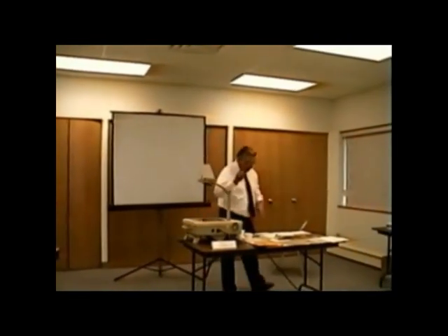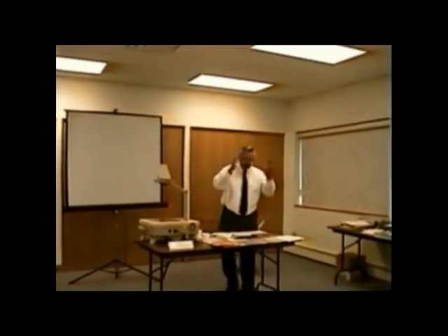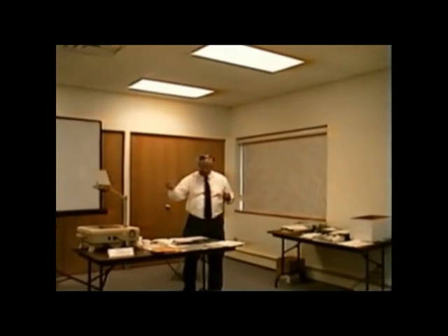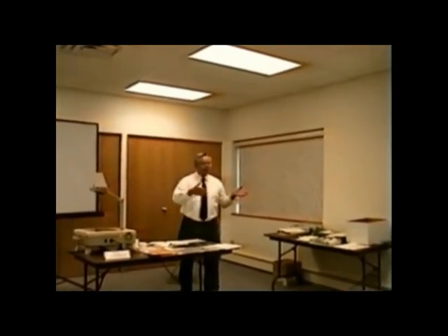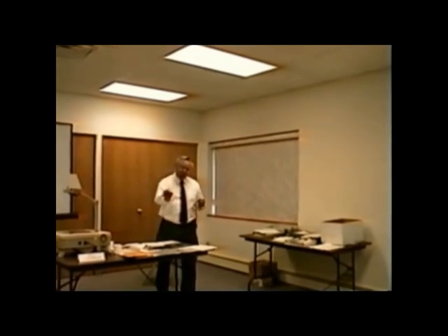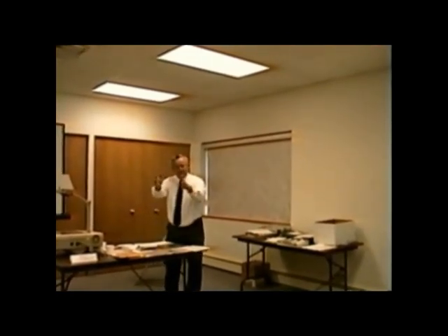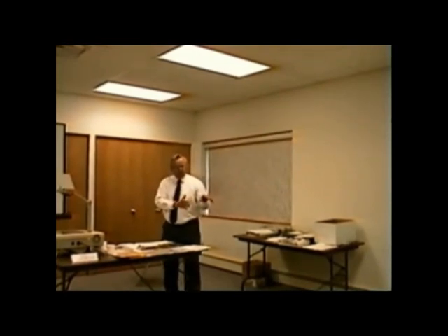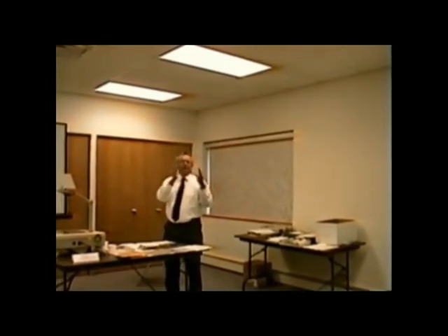So let's talk about one more thing yet. If we're checking temperature for temperature rise, again, we put in our electronic probe, that would be the thermometer, that's a little thermocouple probe. We can put a hole by the return. We want to check the temperature that is coming back to the furnace. So you get as close to the furnace as you can, so we see the temperature that the blower is actually pulling in from the return.